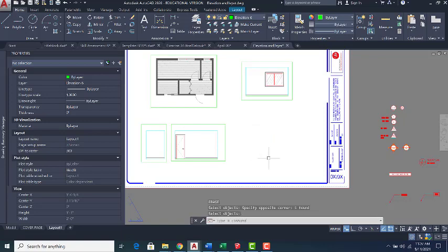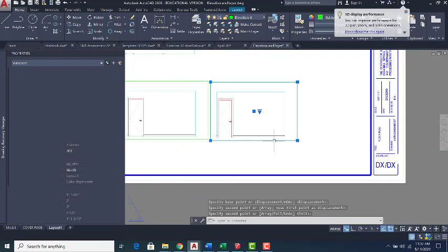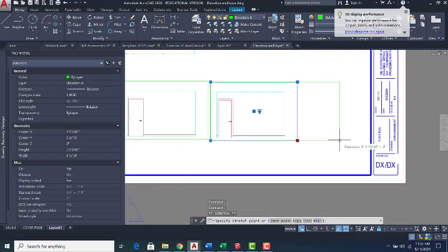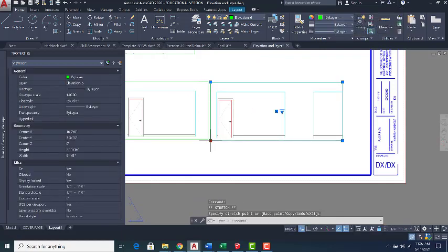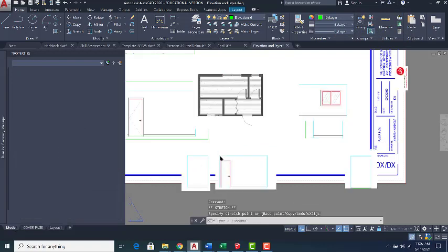Just copy your previous viewport, bring it out so you know you are dealing with the new port, click on it, and then grab the handle. You have to find the next elevation. And it works if you do it the way that I did it.